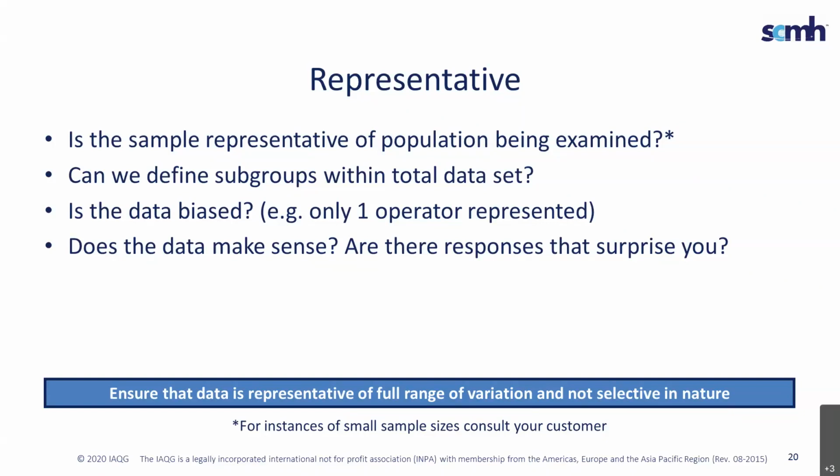All right, now, along with that, this comes into play: do we have subgroups for our samples? And what does that mean? Typically, we take a sample size of 3 to 5 for a subgroup. That's if there is a natural subgroup. It doesn't mean there has to be. Typically, in small batches or lot sizes of 1, you don't necessarily have to have a subgroup, but you should always ask yourself, if I want to be representative, do I take a subgroup?